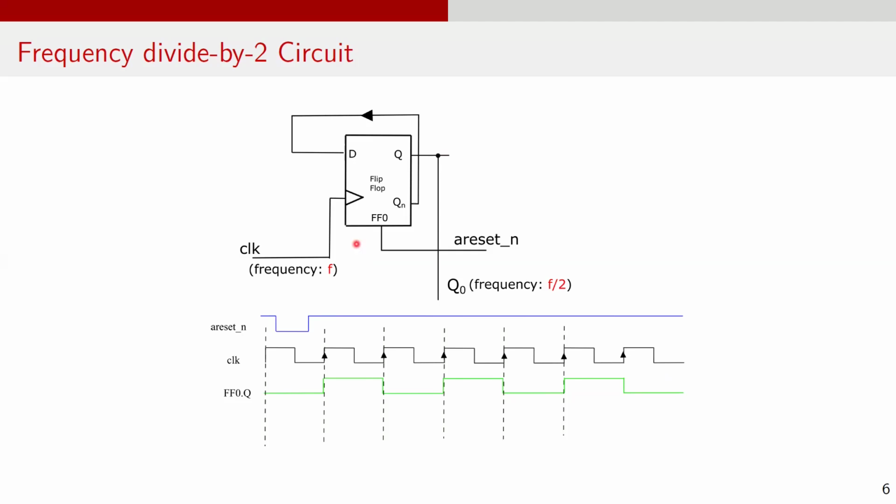In synchronous frequency dividers, all flip-flops are clocked by the same clock signal, so they operate in parallel, unlike the ripple approach in asynchronous dividers, where the stages are triggered sequentially. This eliminates the cumulative delay present in ripple dividers, making synchronous designs faster and more reliable at higher frequencies.